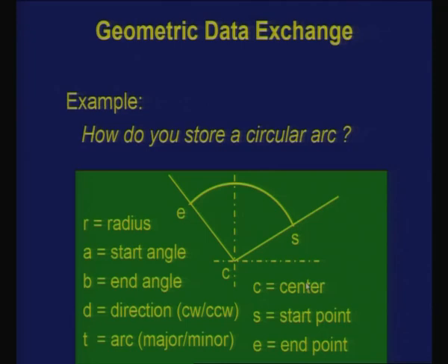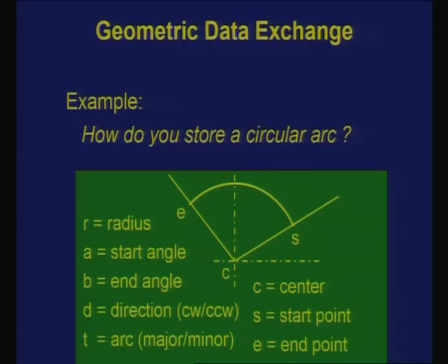Is it necessary to store all this data? Not necessary, because there is a lot of redundancy in terms of information storage. If I am able to store a few parameters, other parameters can be calculated. So, when somebody chooses a format to represent an arc, it need not be true that everybody selects the same set of parameters. Somebody may be more comfortable selecting start angle and end angle, others may prefer to choose start point or end point. Somebody may select center, others may select radius.